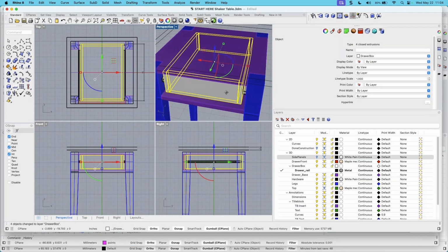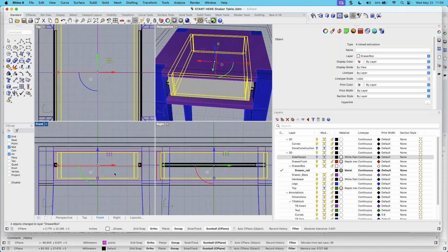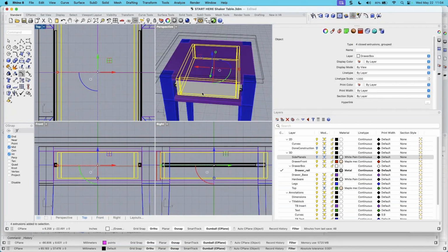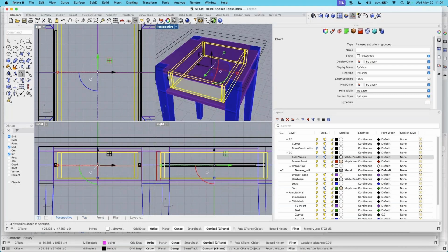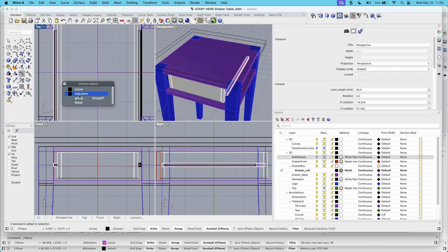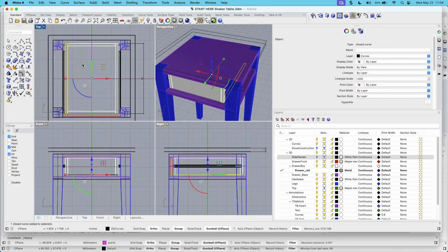So now they're on the right layer. And if you want, you can group them together so they're very easy to select together the next time. The group button right here makes it so that when you pick a set of objects, they're picked at one time. They're not like a block. They're not given a name, so they can be really quick to use.